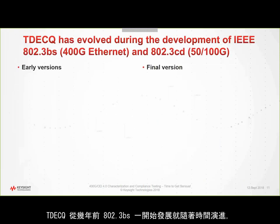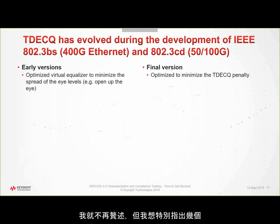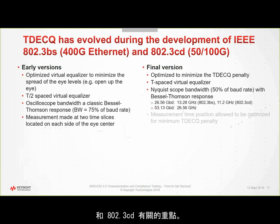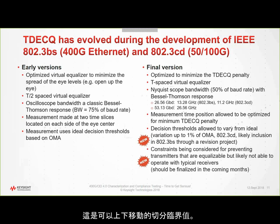So TDECQ has definitely evolved over time, from the beginnings of 802.3bs probably a couple of years ago now, to where it is today with 802.3cd. I won't go through all of these, but the key ones that I wanted to point out were related to 802.3cd. One of them is the fact that the decision thresholds are now allowed to vary from ideal, up to 1% of OMA. So this is a slicing threshold that's allowed to move up and down.